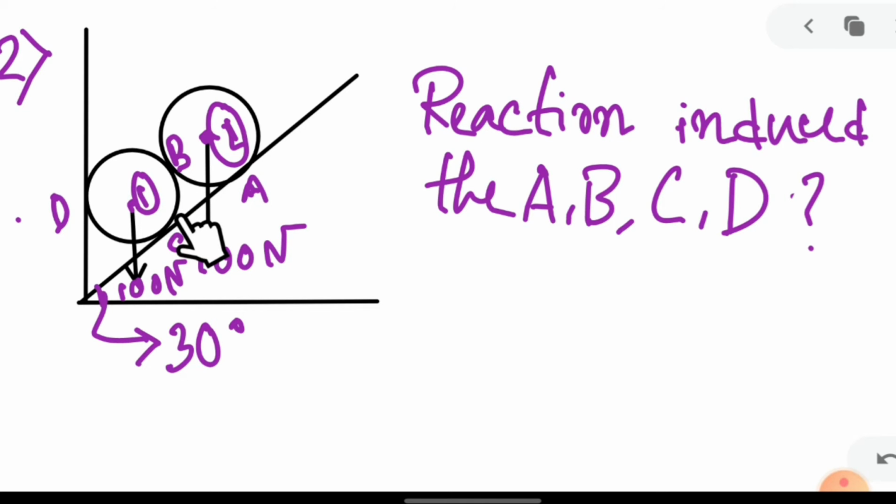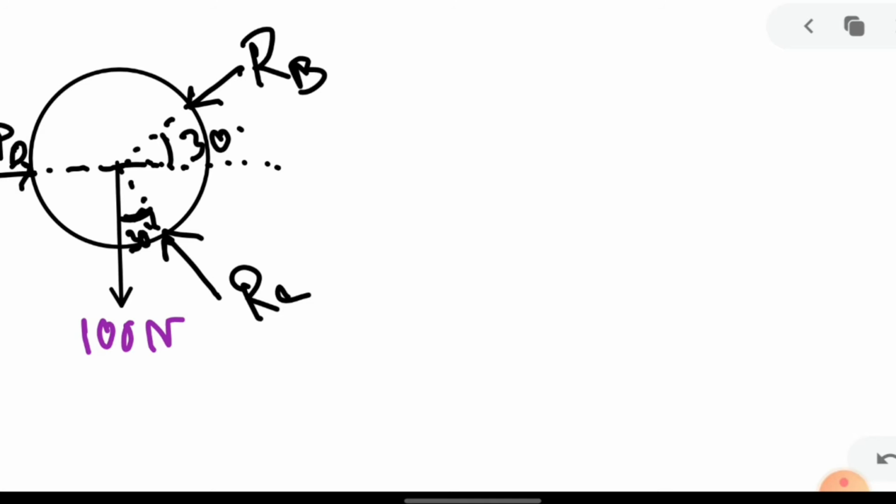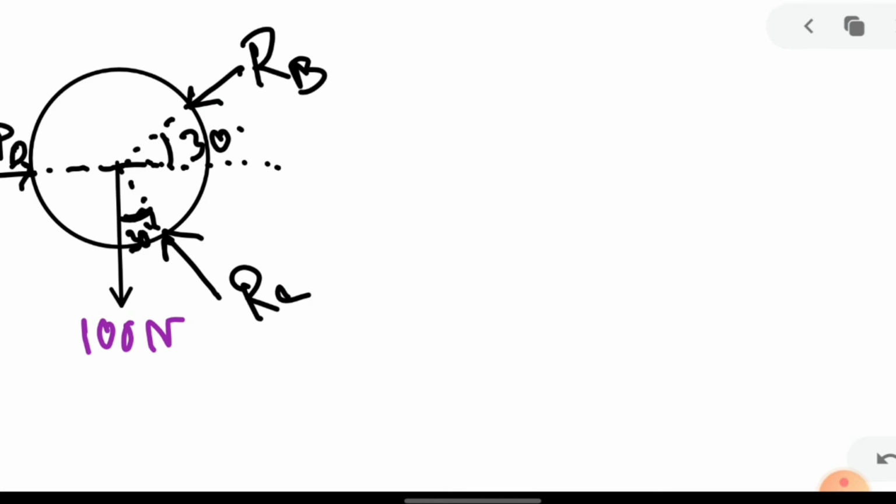It is 30 degree. It is given that in this direction, means it is parallel to the inclined plane, and it is ground surface, so 30 degree. You can see that in this direction reaction force, and ground surface it is like this and this, so it is 30 degree. So now the FBD is done. We just need to now write the Fx and Fy forces.